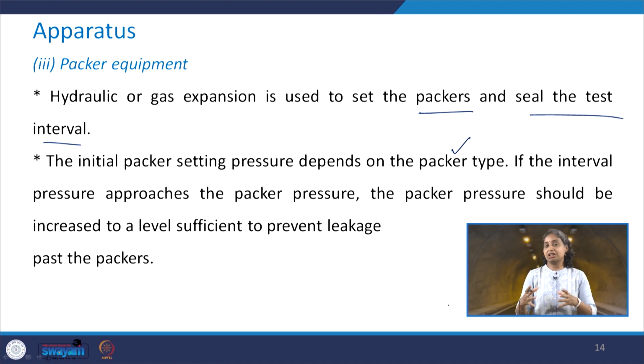Because if the packers allow leakage of the pressure, then the test section will experience a lesser amount of pressure, and then our test will not be successful.